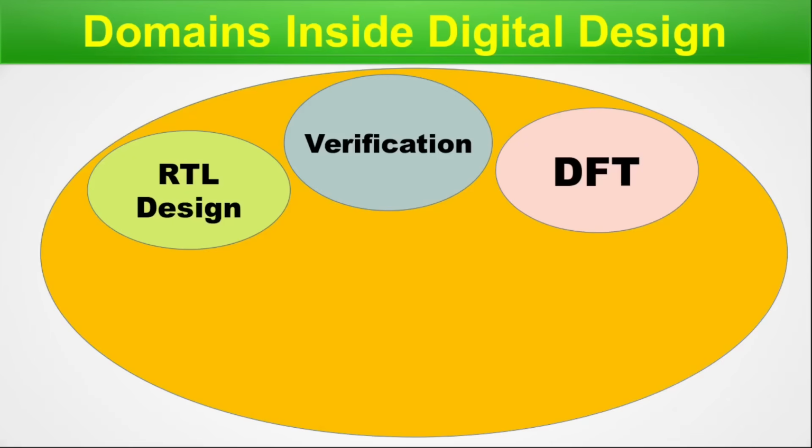Now we are entering into the back end or physical design, and the domains are PNR, CTS, ECO layout. I have captured them inside one single circle. At the very beginning of physical design, an engineer deals with EDA tools for PNR, that is place and route, clock tree synthesis, that is CTS, layout, and its ECO, that is engineering change order.